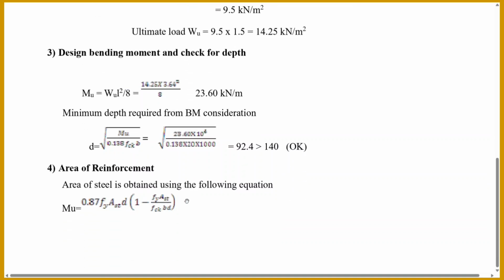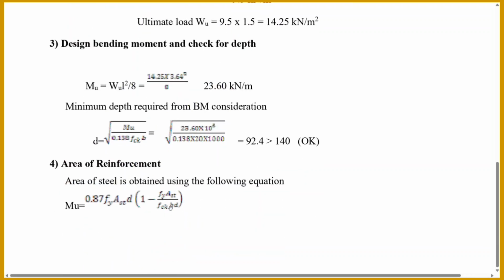140 is greater than 92.4, so our slab is okay in the depth criteria. After that, we will design the area of reinforcement. For that, we will first have to find the Mu.